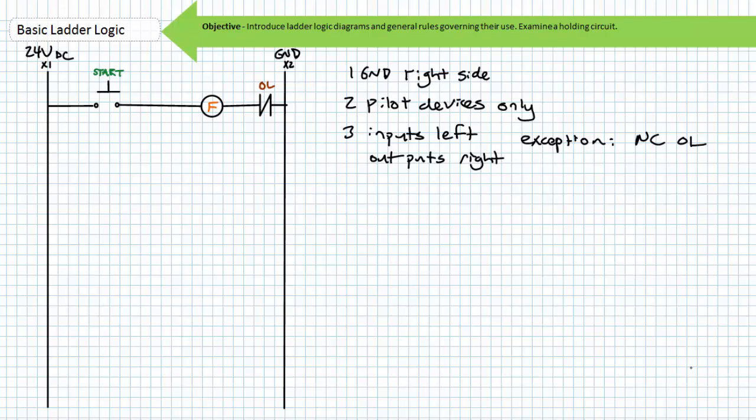When a rung's input devices allow closure from one upright to the other, the load is energized. Outputs normally go on the right. A series connection of two normally open switches means both push button 1 and push button 2 must be simultaneously closed to energize lamp A. This is the logical AND operator, and its function is readily apparent as illustrated by the ladder logic diagram.